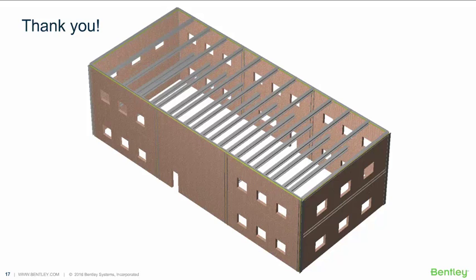Another question: why not use RAM Elements to apply lateral forces in lieu of using the structural system? Yes, you can certainly do that. The advantage of using the RAM structural system for lateral forces is the automatic load generation, right? In the structural system, you have very nice tools to allow for wind and seismic load generation that you don't quite have in RAM Elements. So that would be one of the advantages. But certainly you can also apply the lateral loads in RAM Elements.